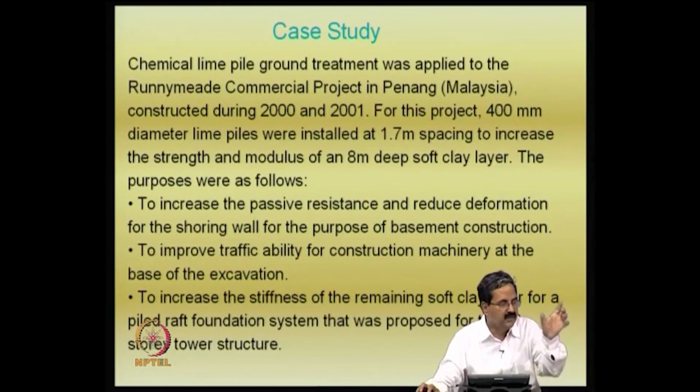Like you have some material in the area, you made it very stiff, and because of that the passive resistance is increased, and because of that it reduces deformation for the shoring wall for the purpose of basement construction, and improves trafficability for construction machinery at the base of the excavation. In fact, if the soil is so poor and you can't even walk, you have to make it a little more workable.